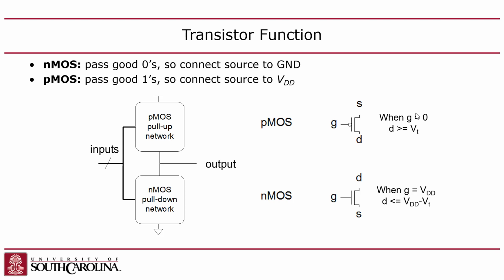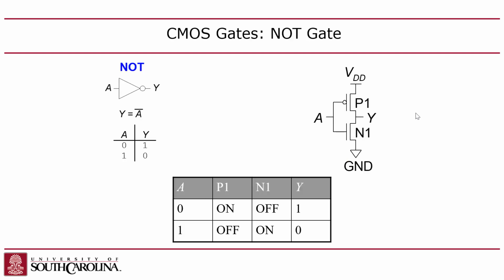One thing I want to mention here, the same inputs connect to both, right? So you notice this fan out here. The fan out means I'm going to connect the inputs to both sides. Also, this is the thing that used to confuse me. These inputs are unaltered inputs. You have to take whatever the inputs are and use them in the gates on these networks. You can't add extra inverters or anything like that. You have to take the raw inputs and connect them directly to the gates of those transistors, right?